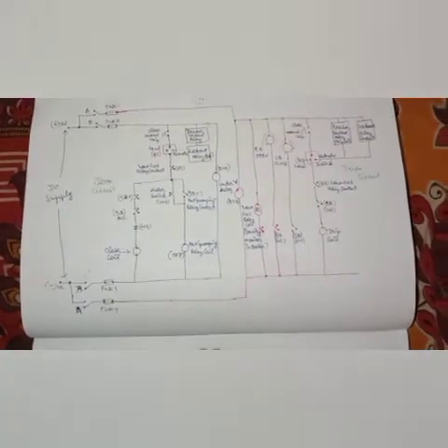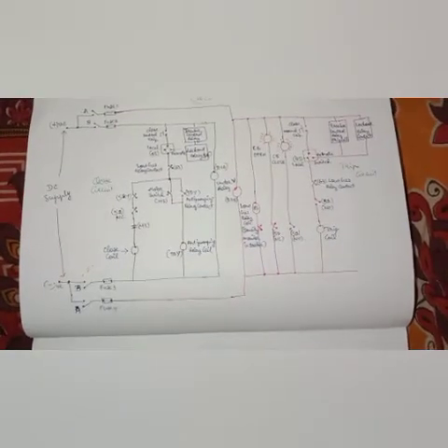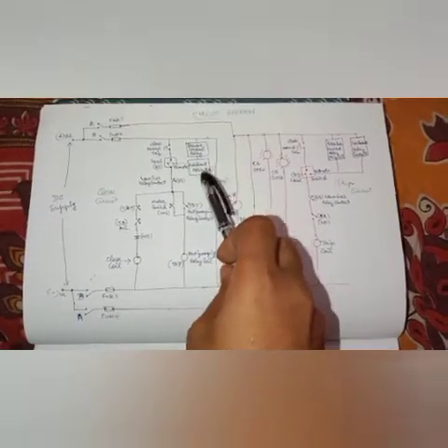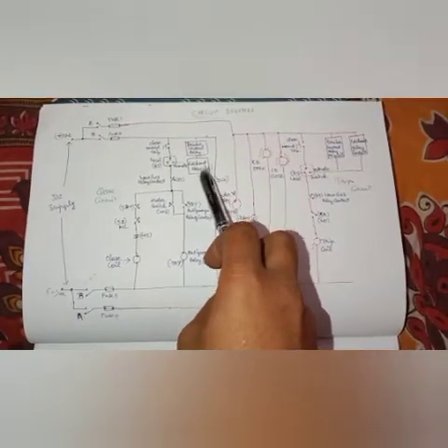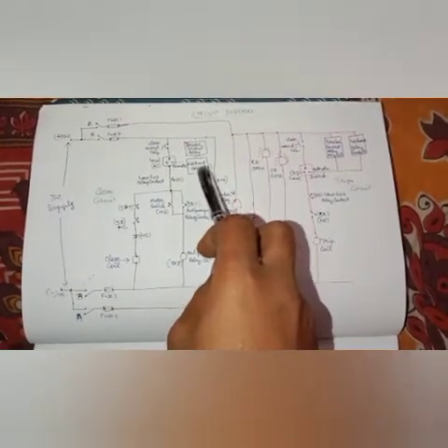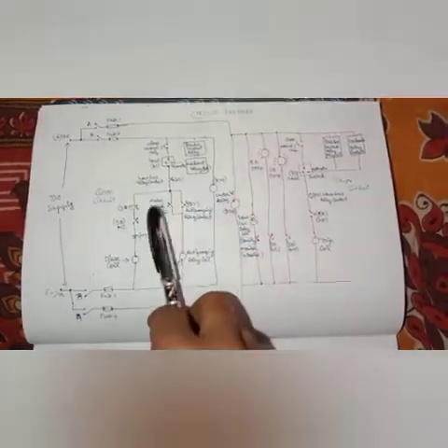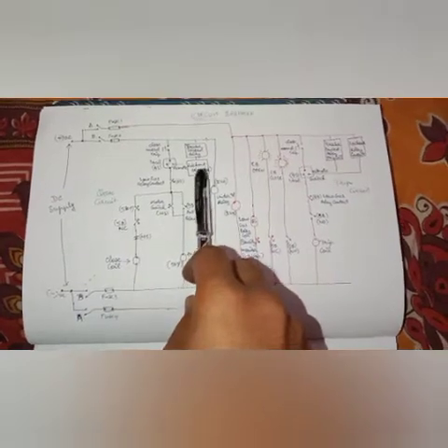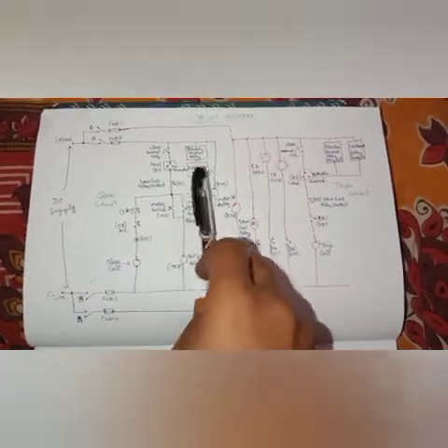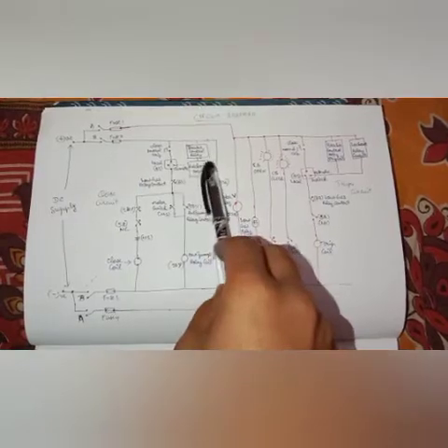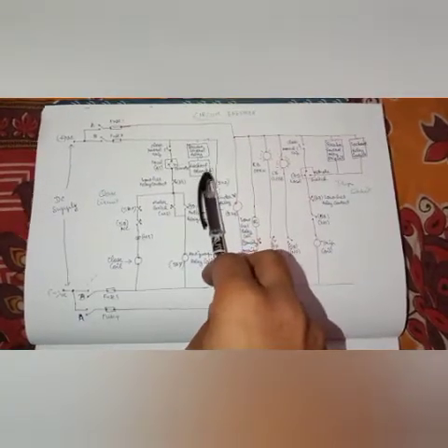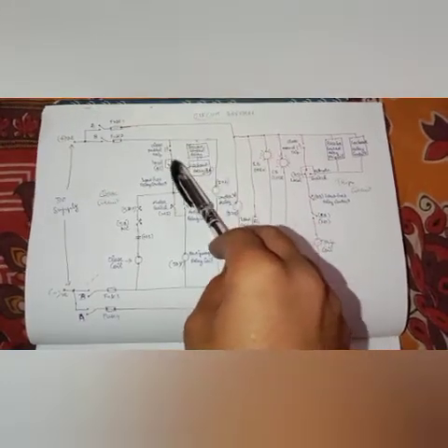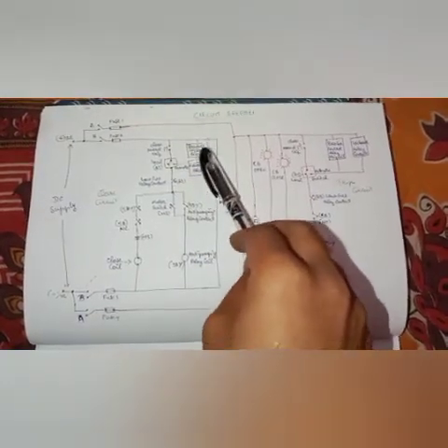So whenever any fault happens, the protective relays will operate and initiate the lockout relay to trip, and that lockout relay, once tripped, will initiate the trip to your circuit breakers also. And without resetting this lockout relay, we are not able to close the breakers. So we need to check that the lockout relay is in a healthy condition or not. And these conditions are connected in series for the closing circuit.